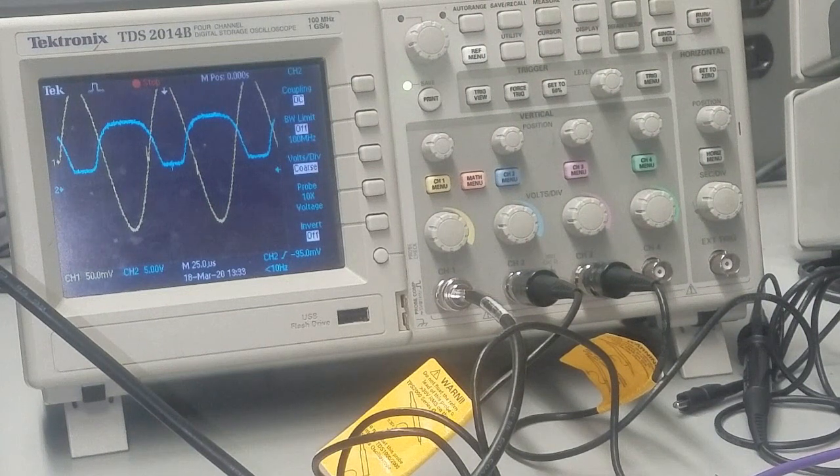So I would expect the voltage at the top will clip very close to VCC, which is the 15 volts. It's going to be a little bit lower than that, and then at the bottom it's going to clip very close to VS, the source voltage. Now remember, the source voltage was around 3.2 volts. So I'm going to use the cursor to determine the clipping from the top and from the bottom.